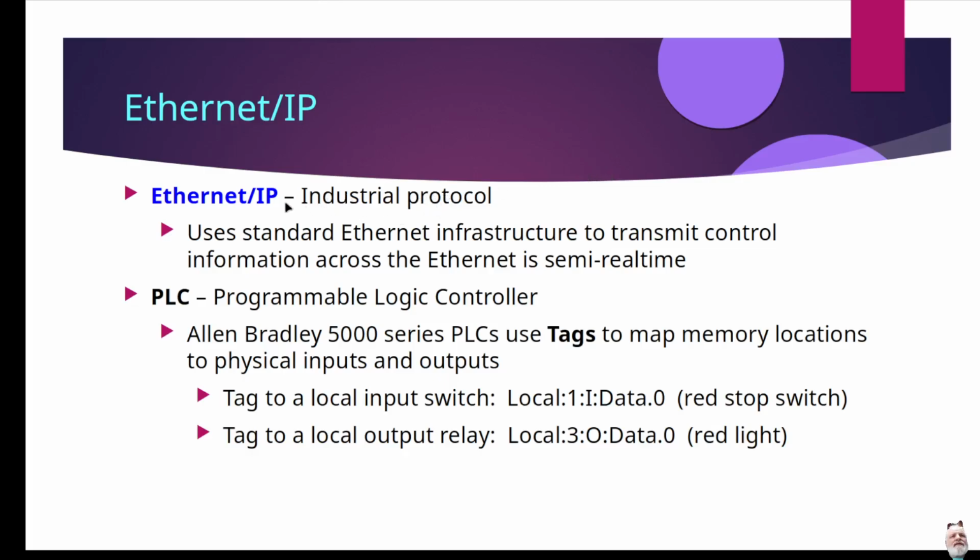All right, so Ethernet/IP, or industrial protocol, when it's written like this, doesn't mean internet protocol. It means industrial protocol, which again indicates that it's got this built-in real time. And the way they do the real time for Ethernet/IP is up there at the application layer I talked about earlier in the OSI layers: the application sends out a timing pulse or a clock signal.